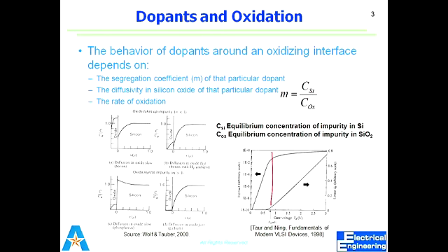If we take this case, you know that the volume of oxide is 2 times greater than silicon, right? Let's suppose that 0.02 micrometer cube is the volume of silicon that is consumed. So the volume of silicon dioxide that is produced would be 2 times that, that is 0.04 micrometer cube.